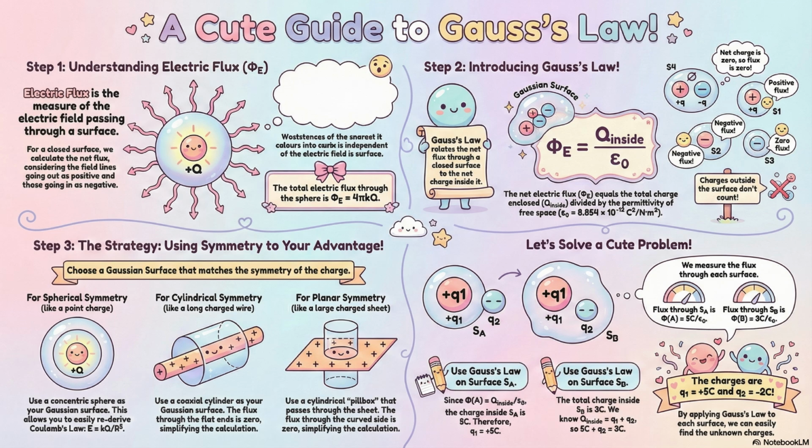Get out. 90% less. As the DC bias approaches the rated voltage, the crystal structure of the ceramic is stressed so much that its effective dielectric constant just drops off a cliff. That is profound. If you're counting on that 10 microfarads for, say, power supply filtering, and you're only getting one, your design is guaranteed to fail.